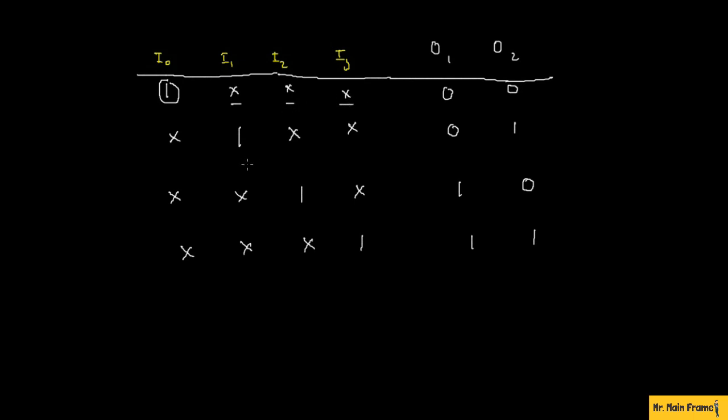Even if you take the third, the second, or any of these from the truth table, you can find this, right? If I2 is carrying data, you don't care about I0, I1 and I3, right? So you are just giving priority to the line that is being enabled to read the data, right?